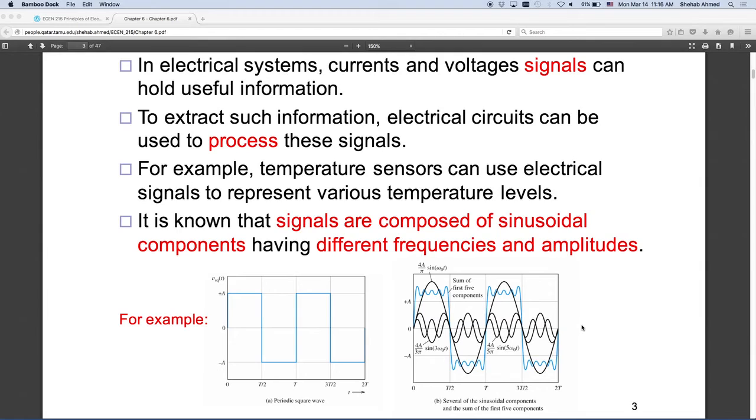I'm going to look at the corresponding output. It will have a certain shape. I can now change the frequency of my input and see what's going to happen to my output, right? So the frequency content in a square wave is very massive, right? Square waves have these sudden changes, meaning lots of different frequency content. So the output will sort of give you the frequency response of that system. Sometimes we look at the frequency response by providing a step function to the system.